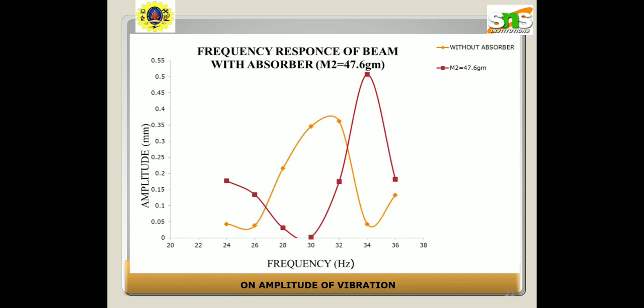Tuned mass dampers are widely used in production cars, typically on the crankshaft pulley to control torsional vibration, and more rarely the bending modes of the crankshaft. They are also used on the driveline for gear whine and elsewhere for other noises or vibrations on the exhaust, body, suspension or anywhere else. Almost all modern cars will have one mass damper and some may have 10 or more. The usual design of damper on the crankshaft consists of a thin band of rubber between the hub of the pulley and the outer rim.